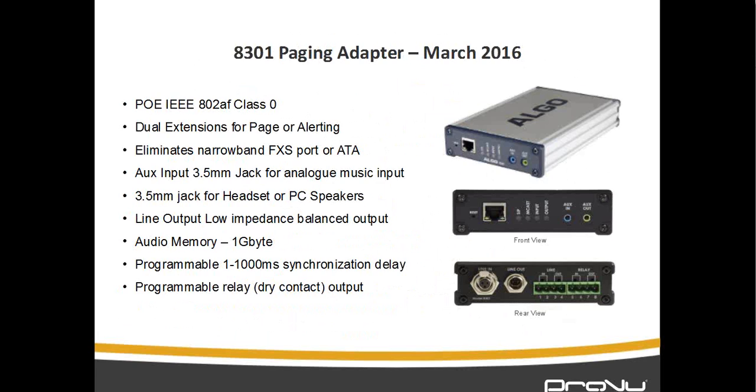But they also have a line output for a proper amplifier, so you can connect it to a balanced amplifier, and it will obviously work that way. It does have a built-in 1 GB memory, and basically you can upload your own music files or pre-programmed announcements, and you can configure it. Everything is configured from a web browser. You don't need any third-party software for that, which is quite good because you're not relying on an actual computer on site. It does have a programmable synchronization delay. All the devices actually have that option anyway.